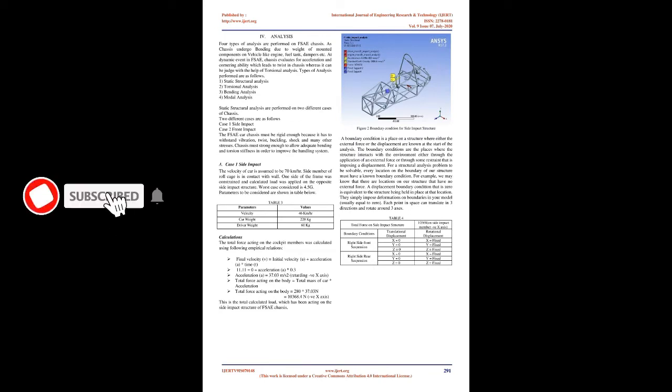2. Methodology. Finite element analysis, FEA, is carried out to determine the stiffness of the chassis frame before construction. Conventionally in FEA, the frame is subdivided into elements. Nodes are placed where tubes of the frame join. There are many types of elements possible for a structure, and every choice the analyst makes can affect the results. The number, orientation, and size of elements as well as loads and boundary conditions are all critical to obtain meaningful values of chassis stiffness.